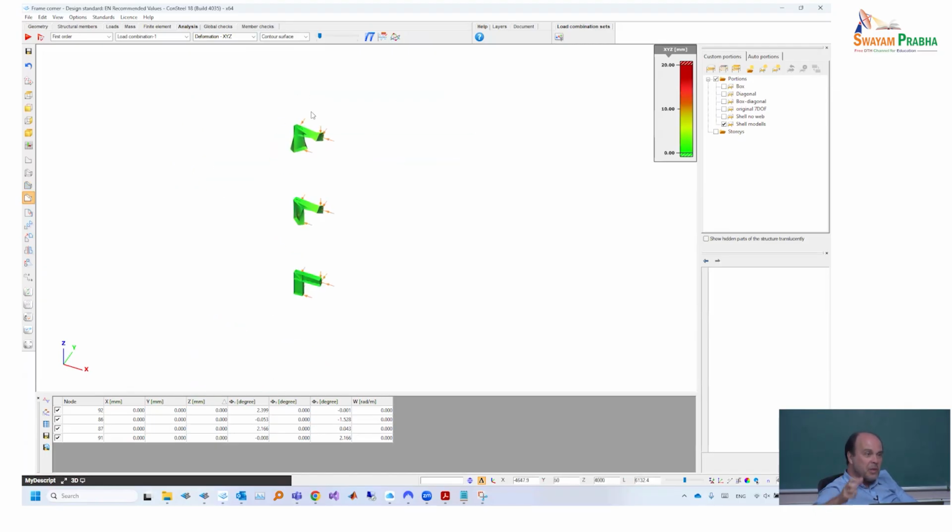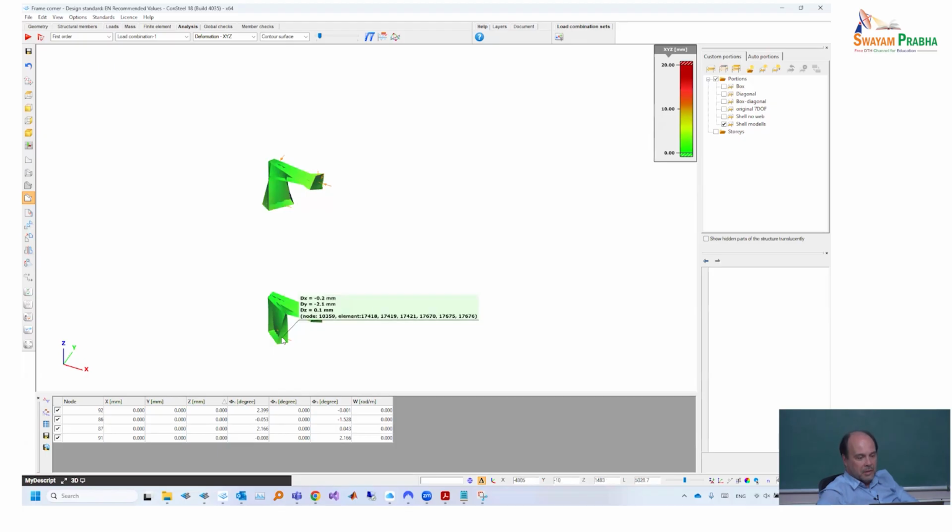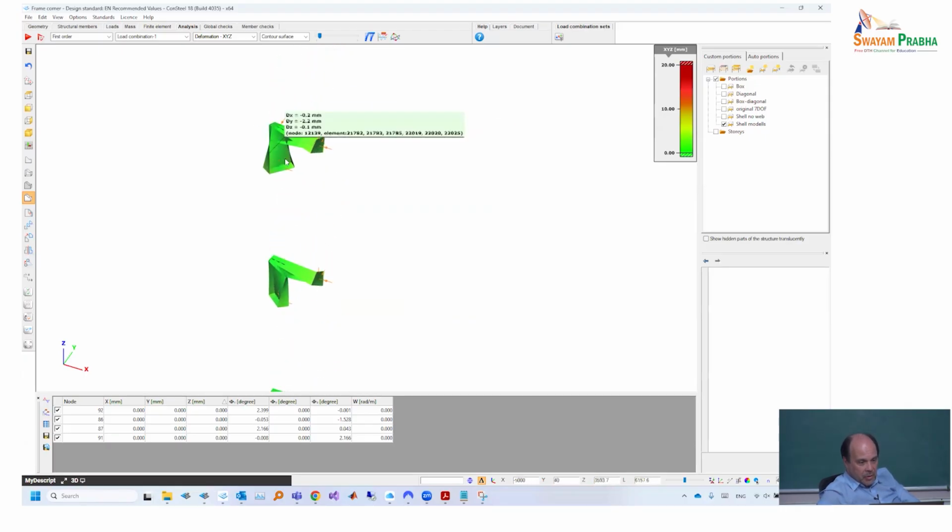So the same rotation is applied on the beam, and then we see what happens with the columns, where the column is free to rotate at the bottom. If I apply the rotation on the beam in the same direction, in one of the cases, the box, the column rotates in this direction. In the other case, the column rotates just in the opposite direction. And in the third, it doesn't rotate at all. And this is something very interesting because normally no one would expect that this happened, and you don't even see it, and probably you don't even know about this.